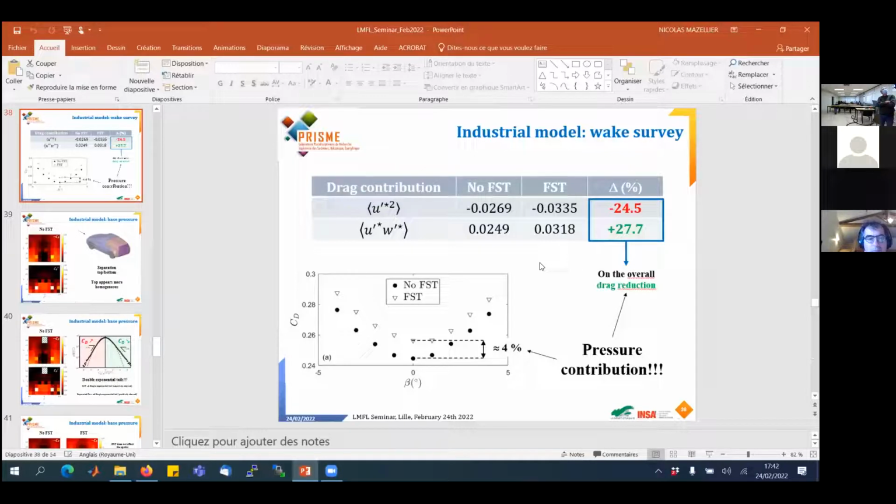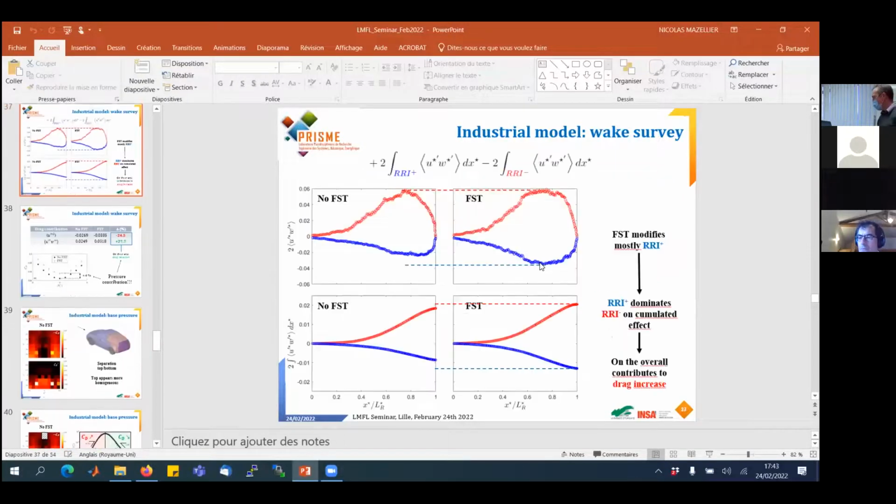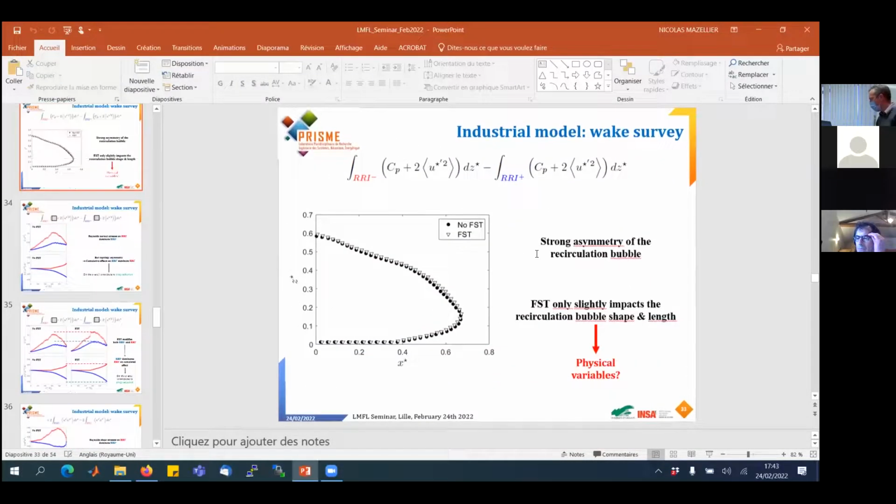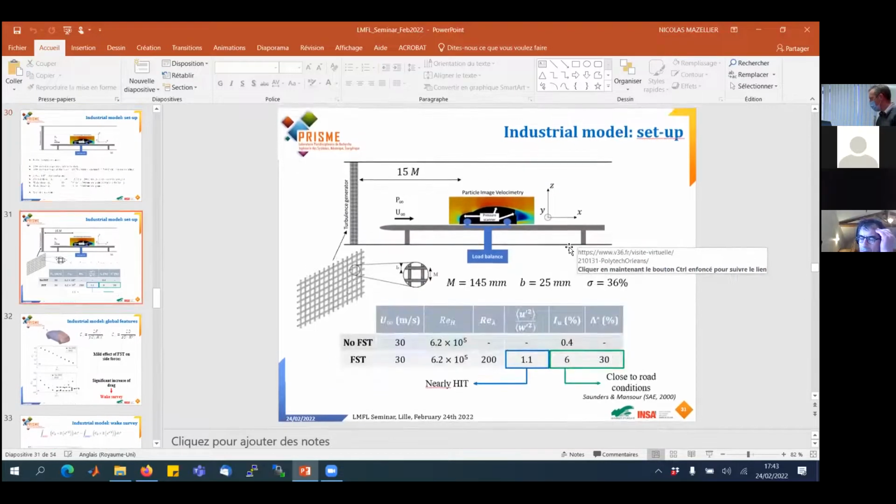Yeah, we correct for this one. It represents something like 0.2% on the drag, in fact. That's very small. Very small, okay. So for the drag itself, it's small. But that's a good point that you have. We need to compensate for the pressure, the free stream pressure measurements. In our case, I'm not sure I have it on the schematic, but I will explain quite easily.